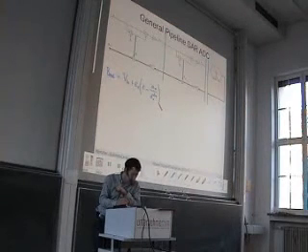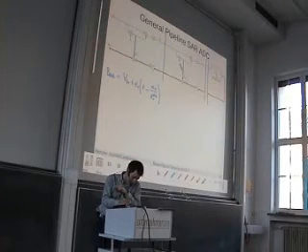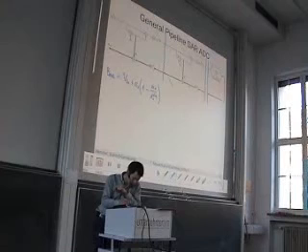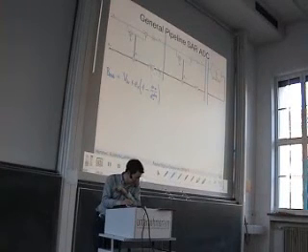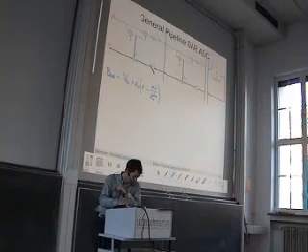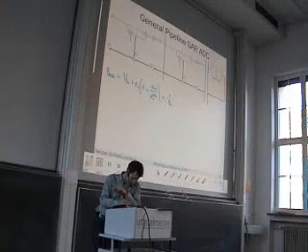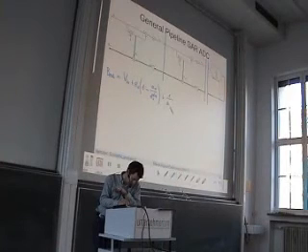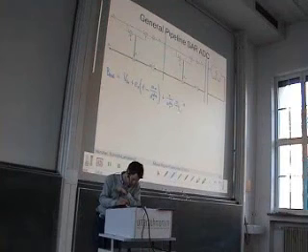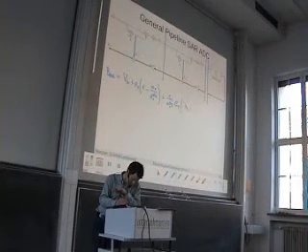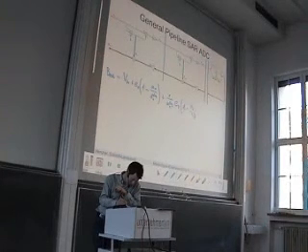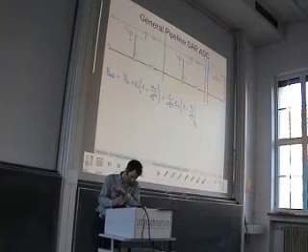Then we have the second quantization error, this one. Well, this one can also take 2 paths and is then scaled by a factor of 1 over A here. So we have plus 1 over A1 digital times E2 times 1 minus A2 over A2 digital. And so on and so on.